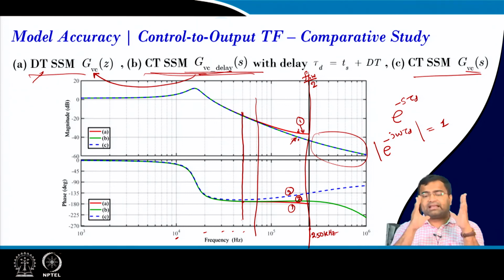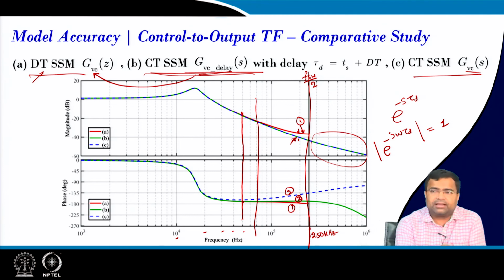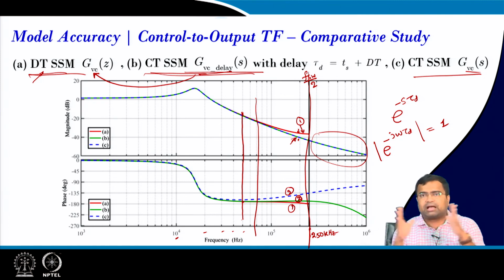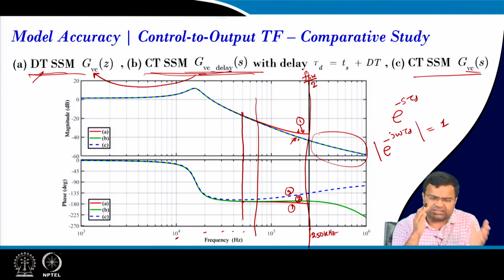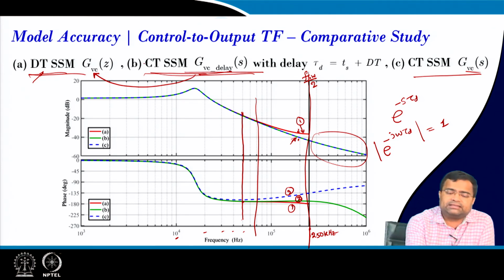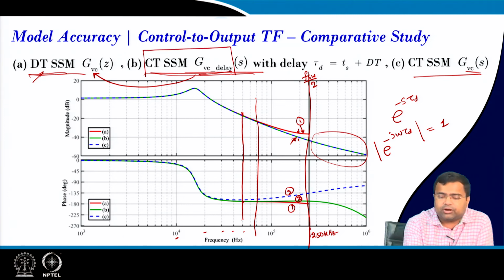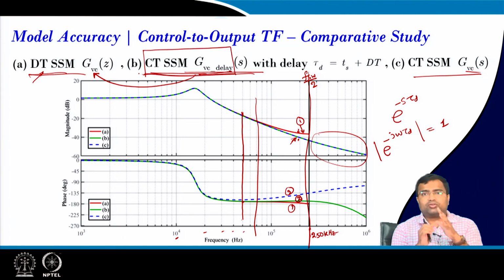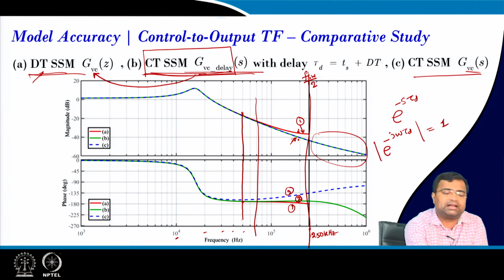We will show that case study during the design, but here we want to make sure that as long as they are stable, there is no subharmonic, then you can design the controller, a low bandwidth controller, I would say 1/10 or 1/5 of the switching frequency. That kind of small signal based controller you can easily design using the continuous time model with delay. But actual stability has to be verified with the small signal discrete time model.